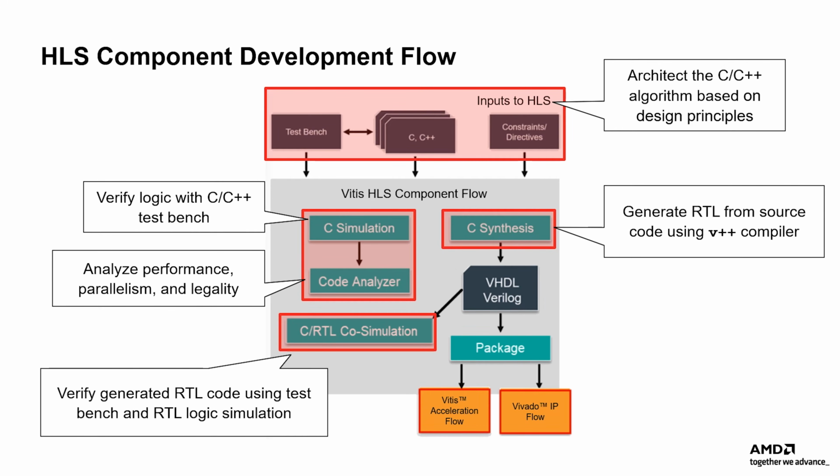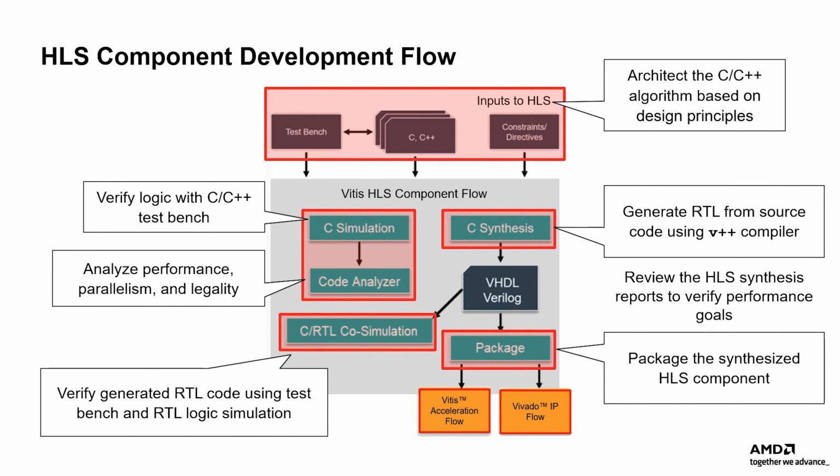Verify the generated RTL code using the C++ test bench and RTL logic simulation. Review the HLS synthesis reports and repeat any previous steps until performance goals are met. Package the synthesized HLS component for either the Vitis Acceleration or Vivado IP flow targets.